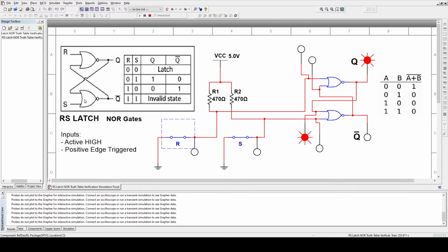Now, I would encourage you to jump on Multisim, in one of the homework labs or the open lab room. Fire up Multisim, watch my previous video on how to place the components and assemble that circuit this way, but you can do it with NOR gates and repeat what I just did. The only thing is I'm going to encourage you to see what I did here. I'm going to stop the simulation.